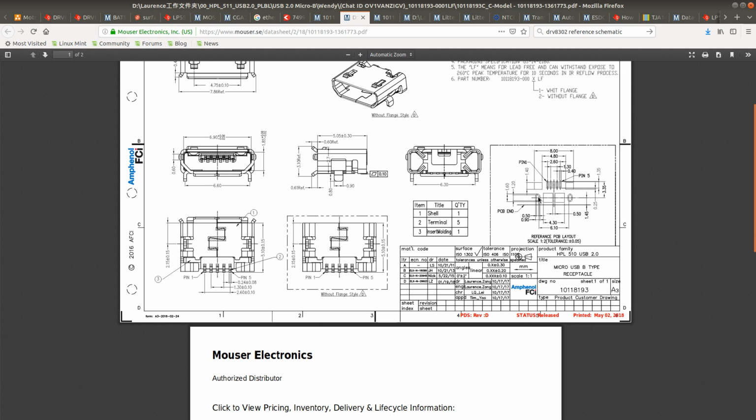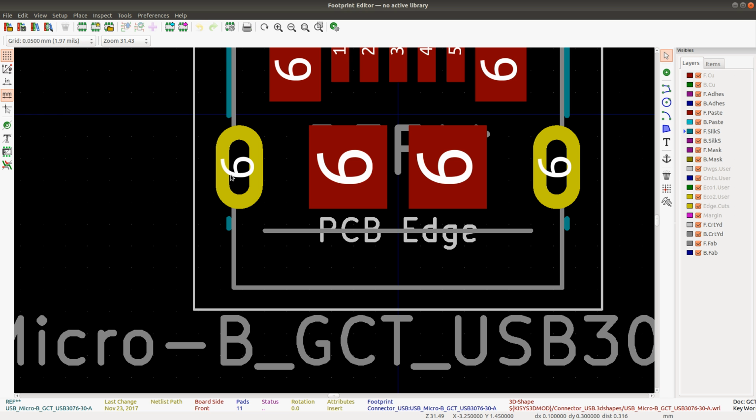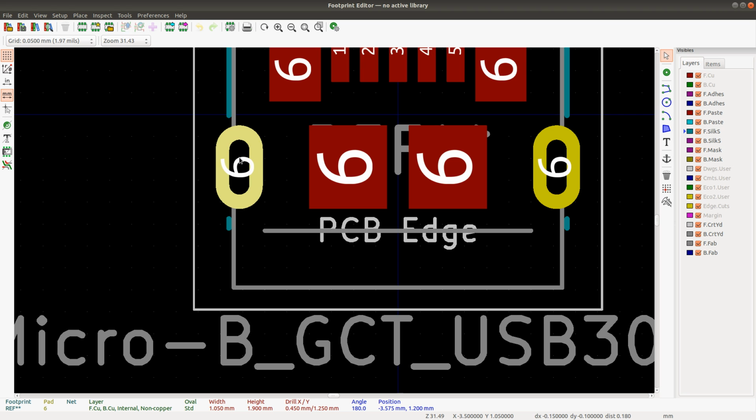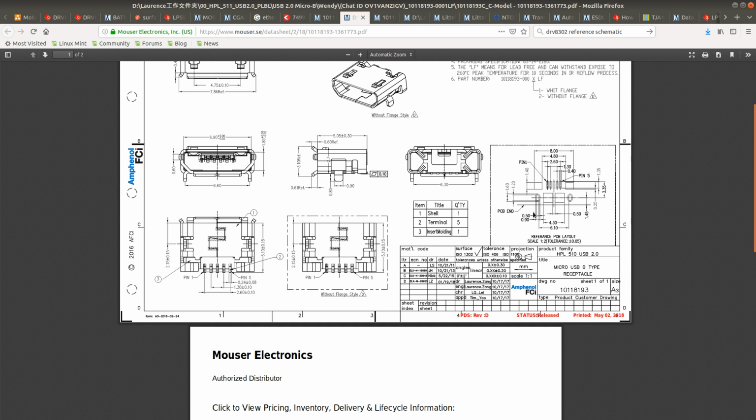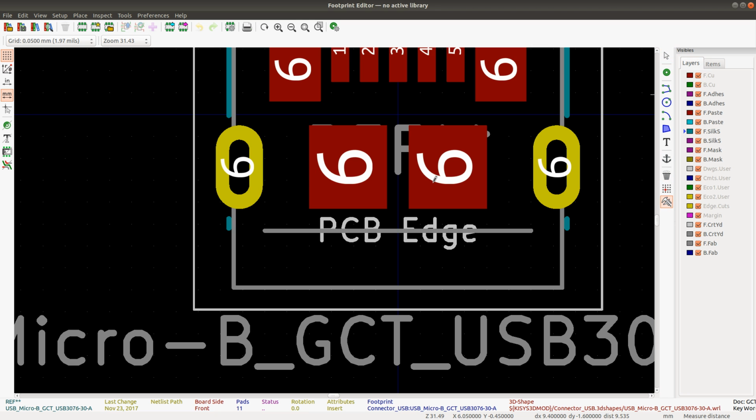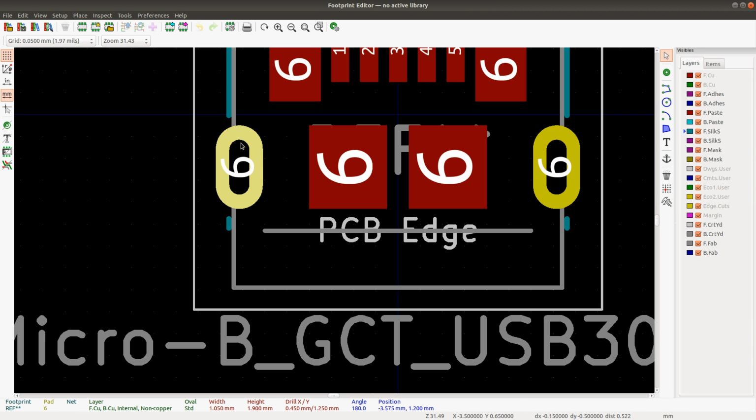So what I have to do, let's place, oh, this is quite odd because they specify the distance from the edge there. Alright, so if I were to place this particular pad, then it has to be 0.5 there. Let's double check this. This is 0.5. This was 0.45, damn it, come on. Okay, we have to fix this footprint.